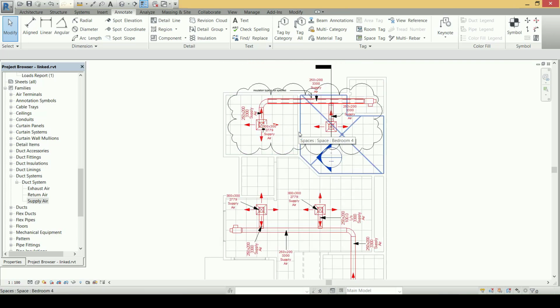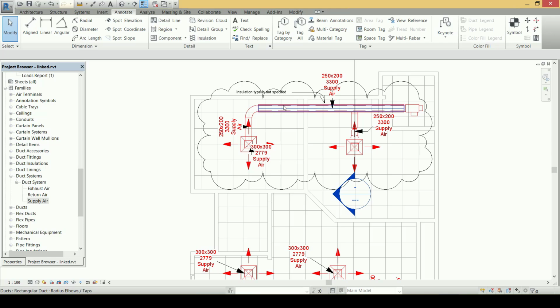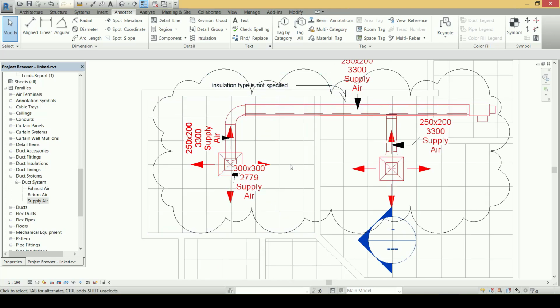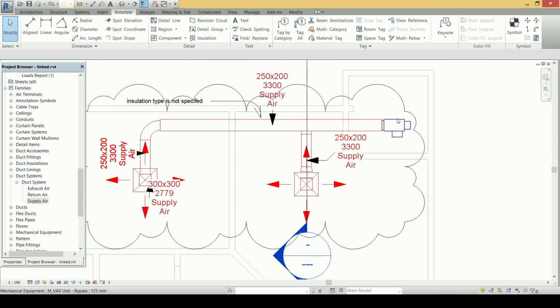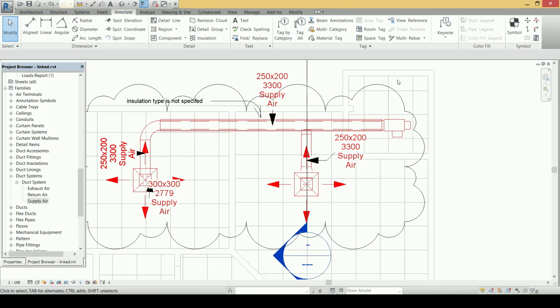Very good. Also, the next thing we need to do is to specify the dimensions of the layout. For example, the distance between each duct and the wall, so we need to specify the distance, for example, from the air terminal to the wall, and the distance for that machine, which is the variable air volume, to that wall or that wall. And we do that for the site engineer to know exactly the location of each component in the real implementation of the project. So we need to express each component position with respect to another known element like the walls, as we know its position exactly.